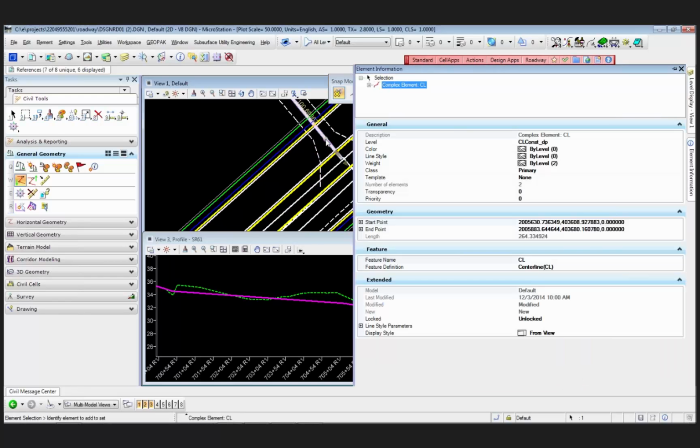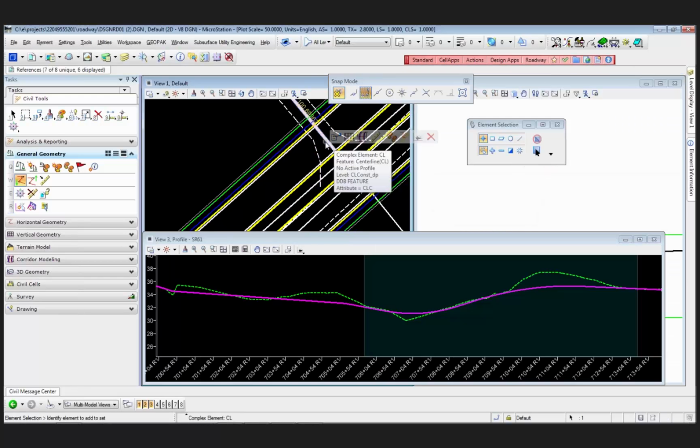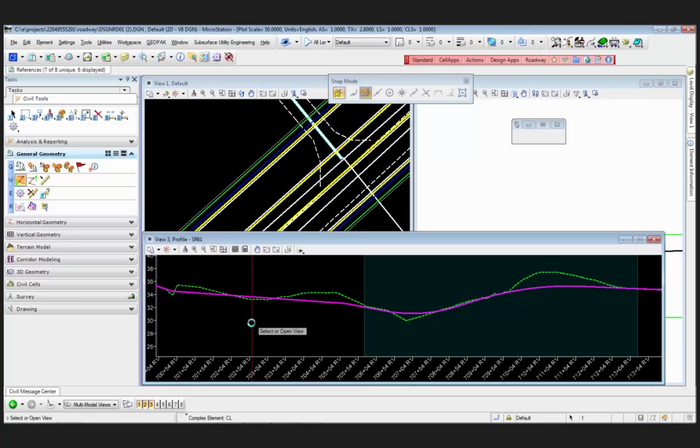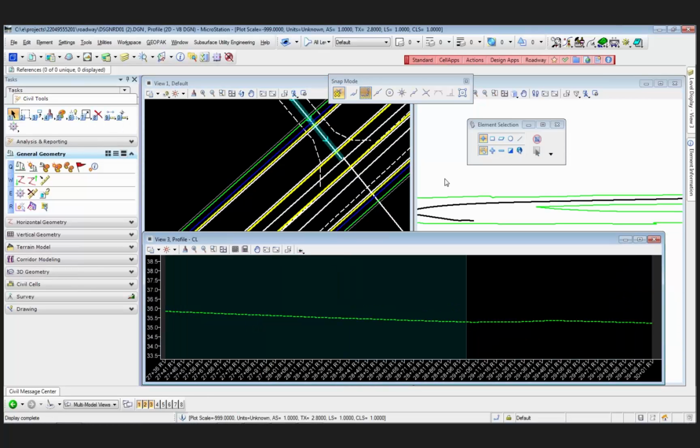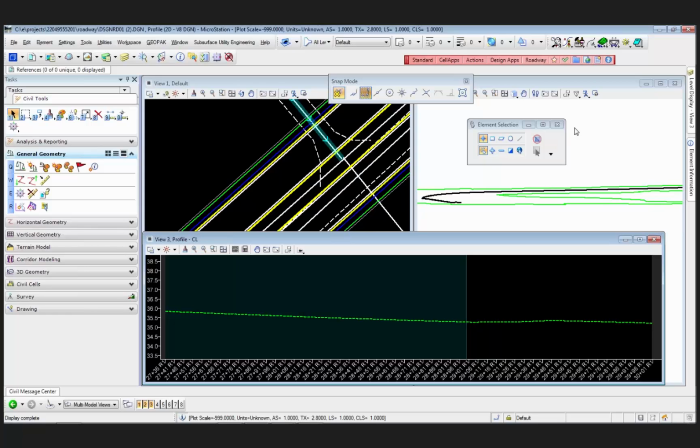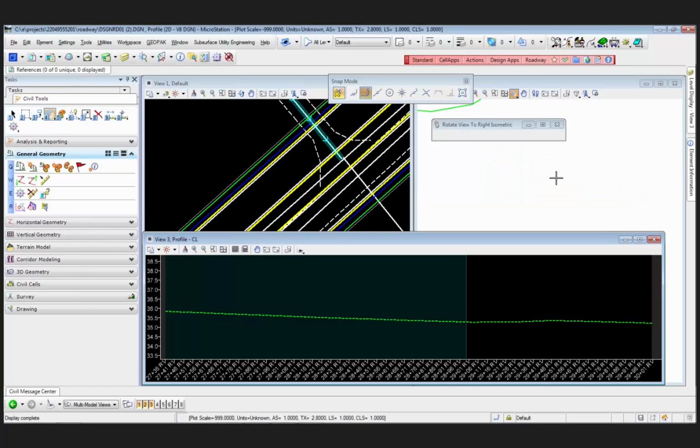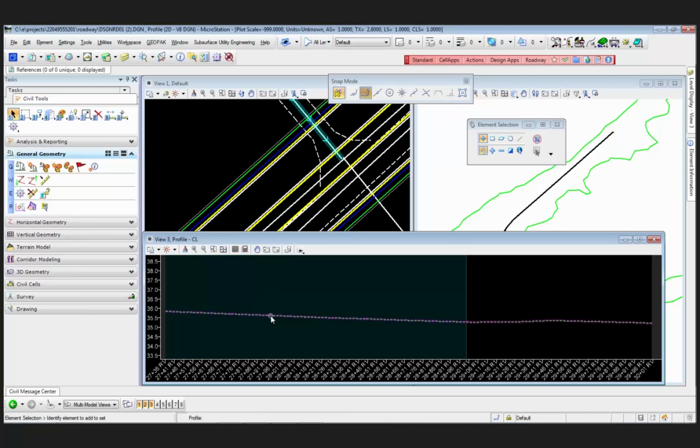And then all I have to do is click on this line and go to the profile model, draw it here. And in order to see it draw in this view, let me go back to a better ISO view, not perspective. In order to see these profile lines draw in the 3D, all I have to do is click on this line and choose Set Active.